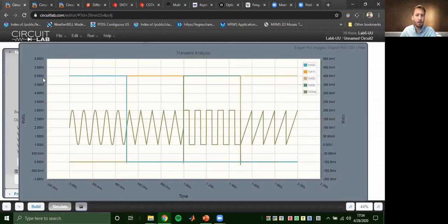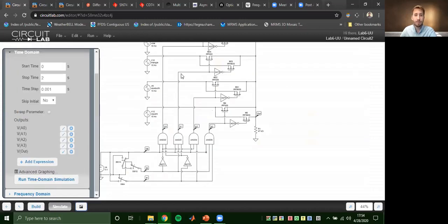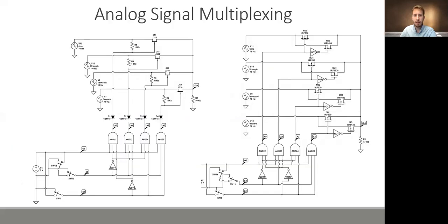I'll pull this back up. As you can see, my voltage here, I was running from 1 volt to 3 volts on my analog in. This can get finicky if you have varying amplitudes in reference to each other, especially if it's running into your 5 volt gate voltage. So ideally, I need a higher gate voltage to be able to get my correct voltage reference. But the gate voltage is only 5 volts because it's logic. I would need some type of amplifying network to get that figured out. But hopefully I could implement this in real life with my circuit that I'm wanting to build someday and get that data multiplexed. All right, so I think that's all for that.